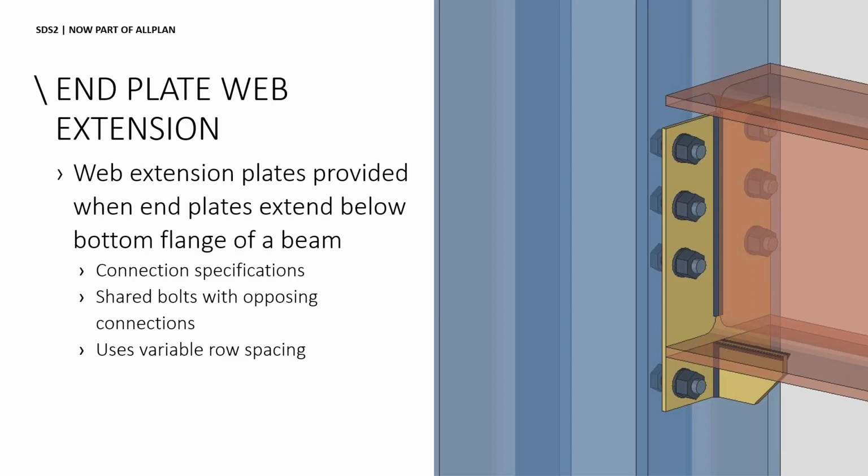Colin, one question for you on this. So one thing to point out is there is no weld on that bottom flange, and that is done intentionally, correct? Right. We wanted to keep this a simple shear connection. So if you added a weld of the flange to the end plate, that would make the connection much more rigid. So you start taking some moment. So to avoid that and keep it flexible, we are not welding the flange to the end plate. Okay, very good, very good.